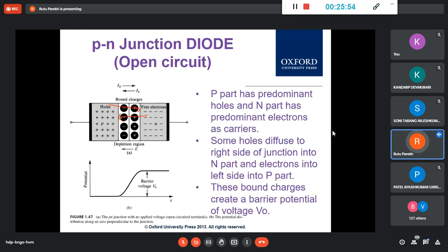So the point here is, if you want a current, that is, electrons to move, it has to overcome this potential. And with no voltage applied, it can't overcome. So the first thing is that there is diffusion. Now it is like a wall, the Great Wall of China. It will not allow anything to come and go, and that current is known as ID, the diffusion current.